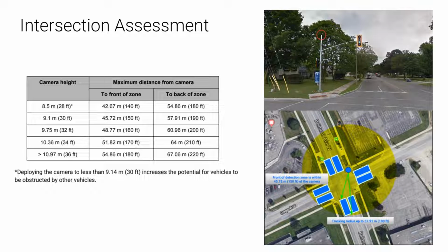It's also important to note that 2 cameras can run off 1 processor. So on abnormally large intersections where you can't see the entire intersection, including the back of the stop bar as well as all the crosswalks, you can easily add another camera to view the entire intersection.